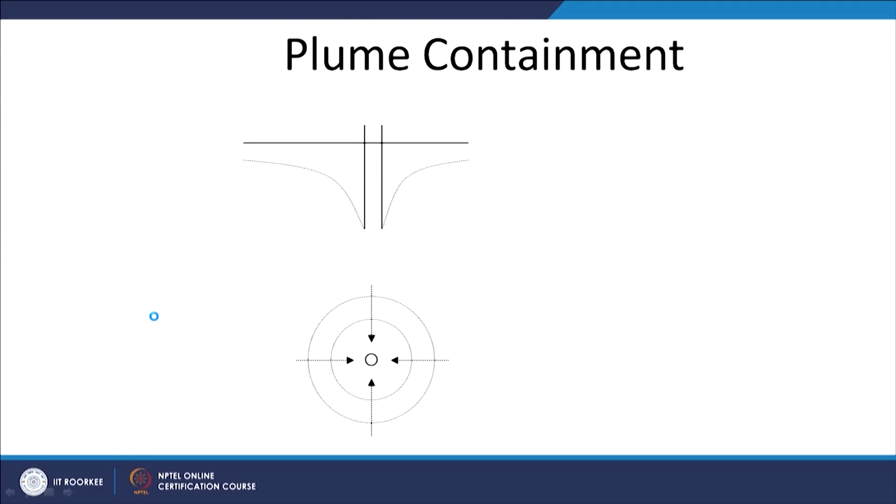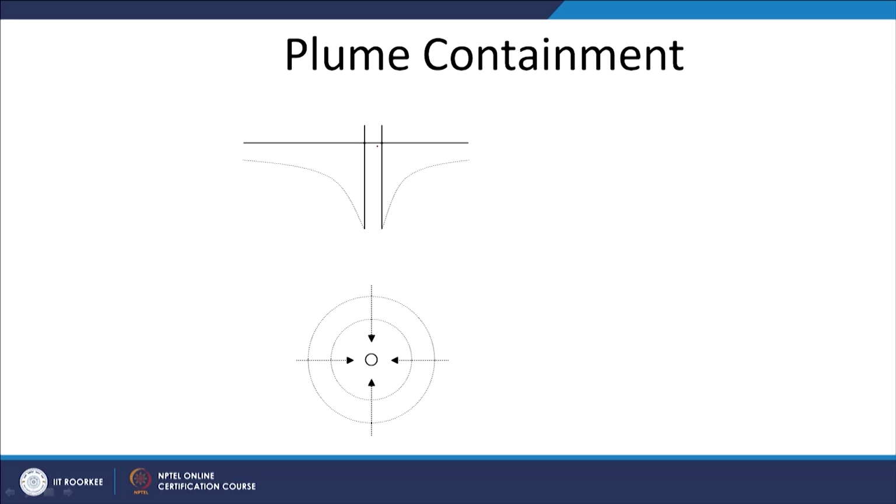So how do I contain a plume? There are different aspects, as in I can put in barriers. That's something we are going to discuss later. As in I can have barriers around that contaminated area, if feasible, so that there is no transport of the contaminant from that site to the groundwater. But for example, I have a contaminated plume and I do not want to let it migrate further. So what can I do? I can pump it out, let's say. And what's the issue here?